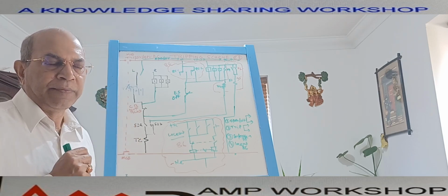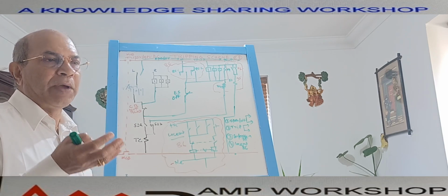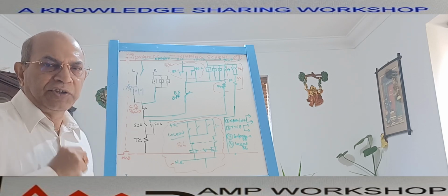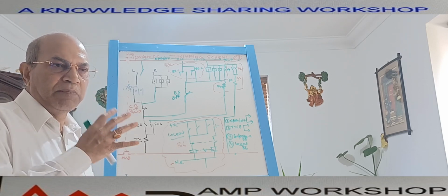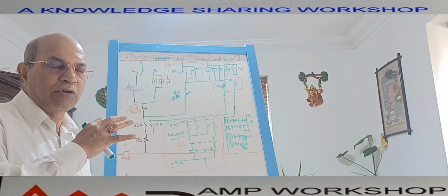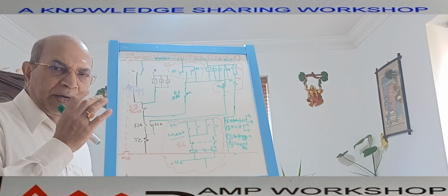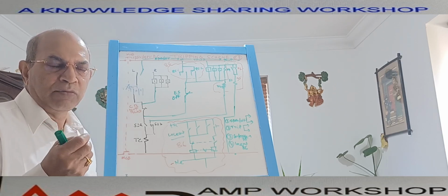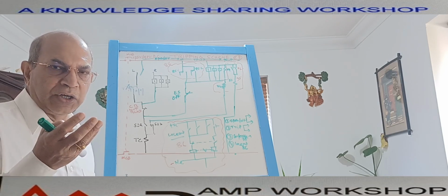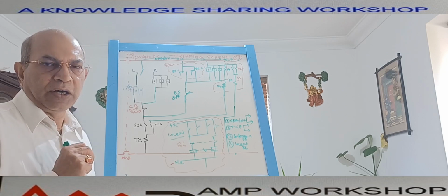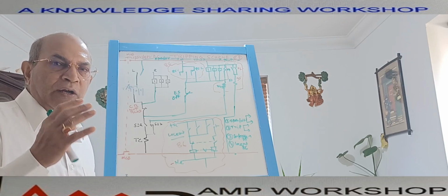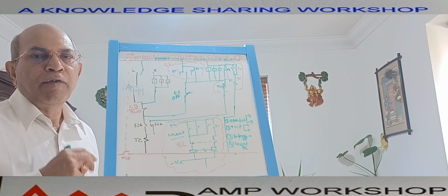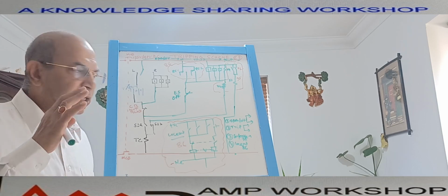In addition to this, there is another feature of this tripping scheme, the lockout relay feature. In this tripping scheme, the breaker will be tripped on fault through the tripping relay. Nowadays we use digital relays whose output contacts are not highly rated, and there is some interlocking requirement. For that we use another lockout relay. Through the lockout relay, the circuit breaker actually gets the fault tripping command. So this is another feature.